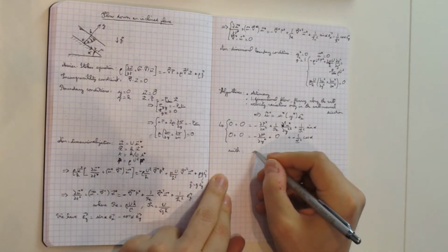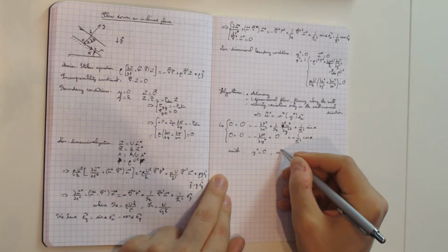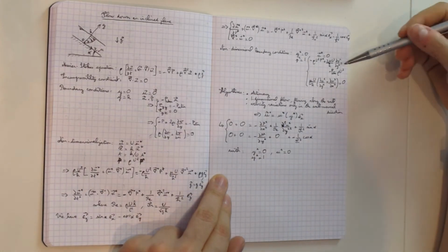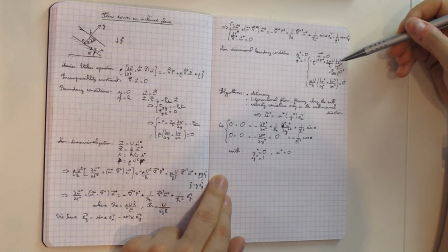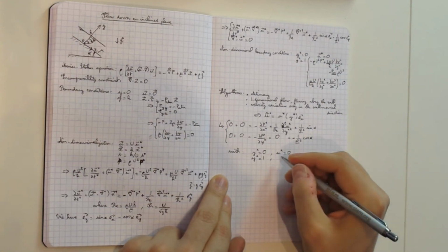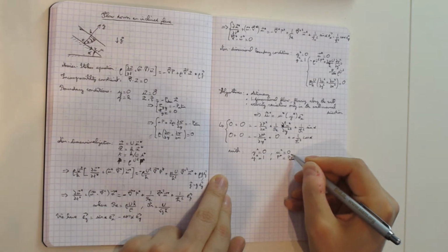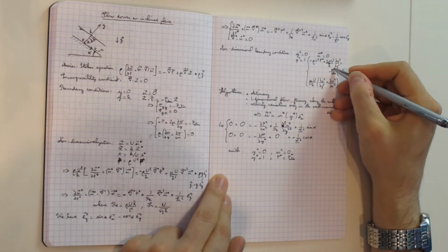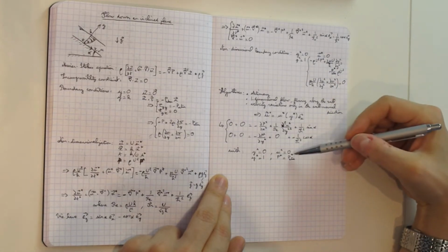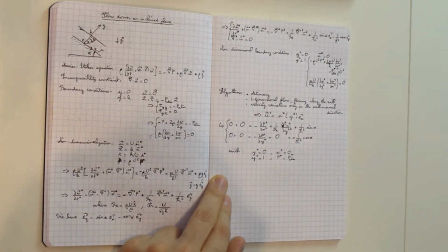Okay, so these are our Navier-Stokes equation, and I can simplify these boundary conditions by writing that at y star equals 0, the velocity has to be 0, and at the same time at y star equals 1, that's my wall boundary condition. So you can see that now we can simplify things here, particularly this dv star by dy star is 0, and so what we get here is P star equals P atmospheric star. I forgot a star here. So what I did here is non-dimensionalizing the atmospheric pressure by rho u squared. So this P atmospheric star is also non-dimensional. Well, you can keep rho u squared if you want here, but then don't put the star.